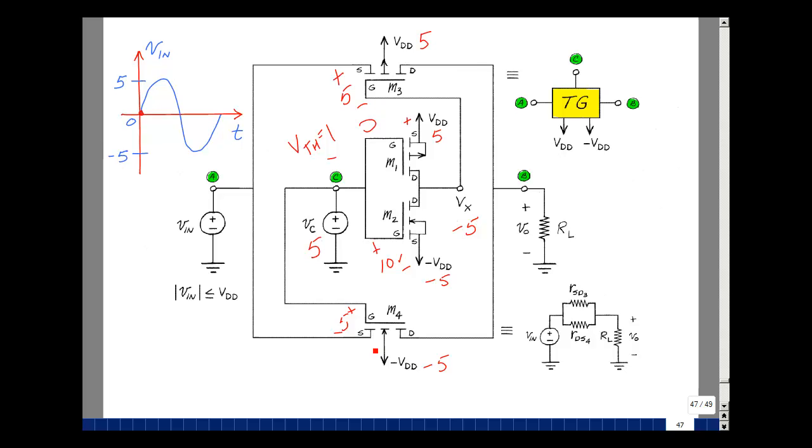And you can think of these as resistors between here and here. They're about the same value in resistance if they were identical transistors. Suppose the value of that's maybe, say, 10 ohms. My analog signal is coming in, starting out at a little bit positive. What's the output voltage? Well, suppose that the load is 10K, where it's much bigger than the 10 ohms. I got a voltage divider of 10K over 10K plus 5, these two equal in parallel, times Vin. Pretty much a gain of 1. I'm passing the signal by putting a logical 1 on the control line.